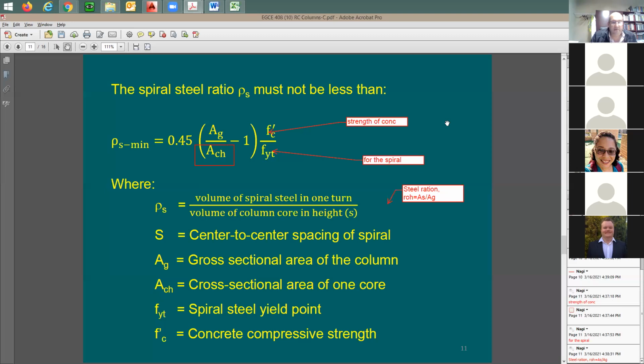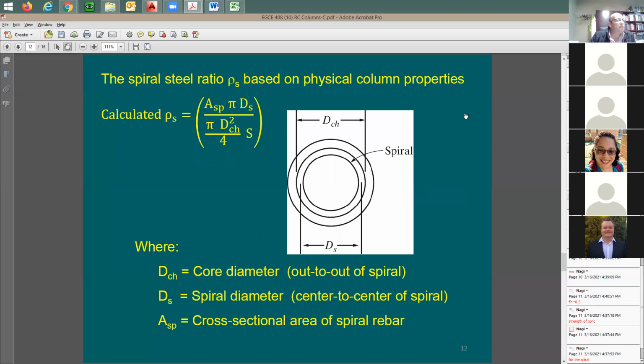I missed the first part of your question. If I have the square root of f'c, so an equation that says f'c to the power of 0.5, does it have to be in psi or is it okay to do it in ksi? Yeah, you would need to do it in psi, the same as if you had addition or multiplication within a multiplying factor of the equation. Okay, thank you.